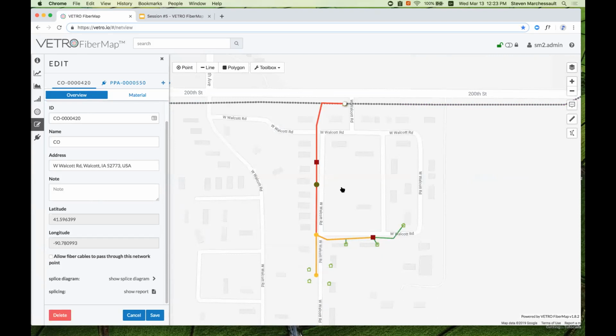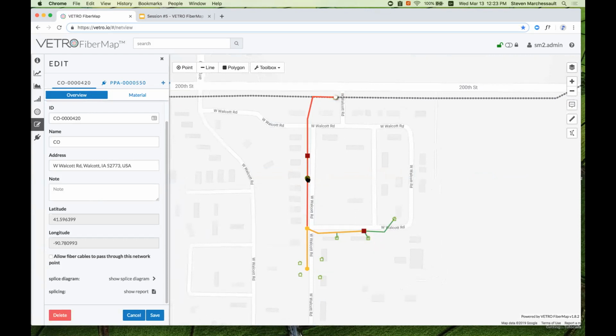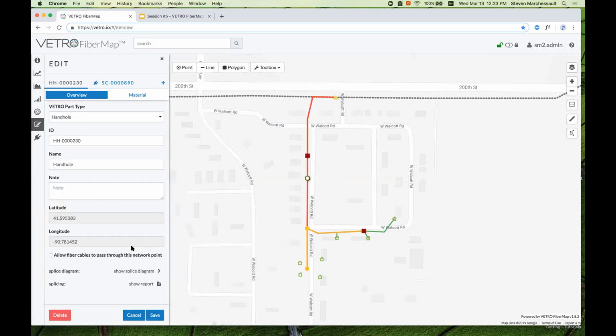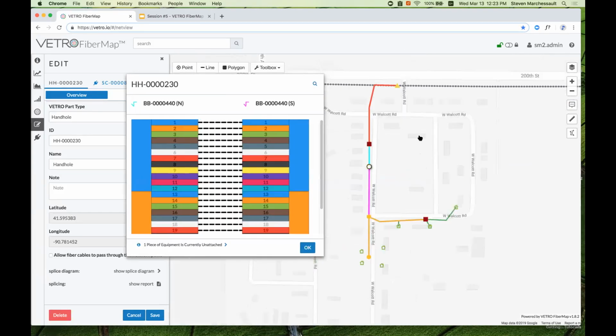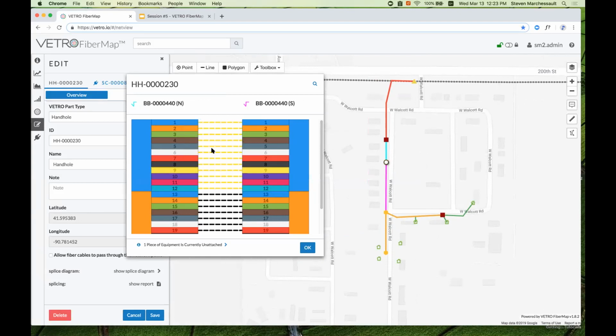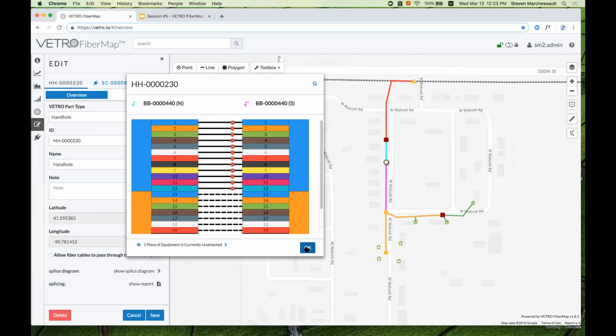The next thing that we want to look at is this cabinet and handhold that I added here as add-ons, just to show you some of the additional modeling, kind of the one-to-one for the splice closures. So these are all represented as pass-throughs. I'll just cut these first 2 buffers and attach the splice closure to all of these. And now if I just shift-click both sides and splice, all of these strands are now passing through a splice closure. And we'll see how that's also modeled later on in the circuit reports and the splice reports.